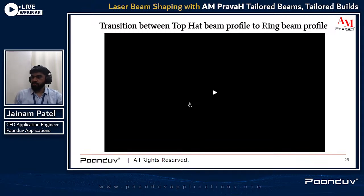Yes, we can also create a pulsed shape. We have to provide the laser on and off time. So for a specific time the laser is on, then we have to provide the scan speed track. There the laser is off, then again the laser is on, and the user can create the pulsed laser also by using this technique.